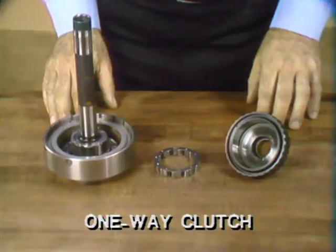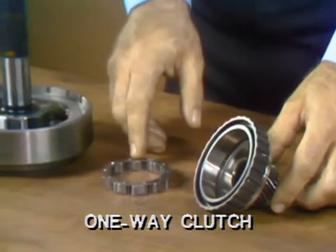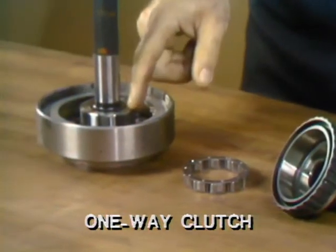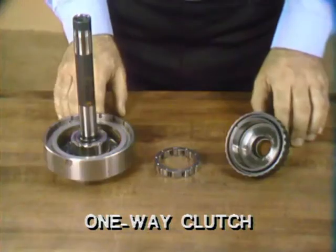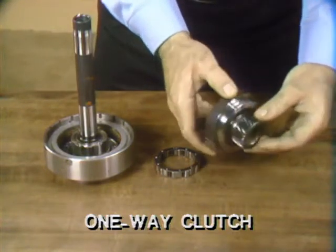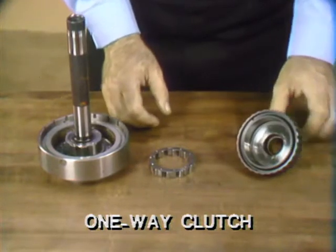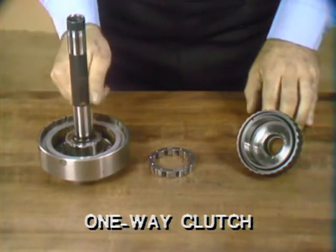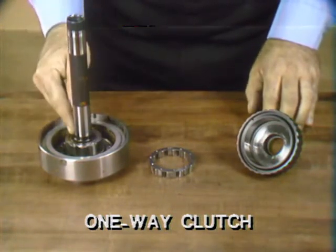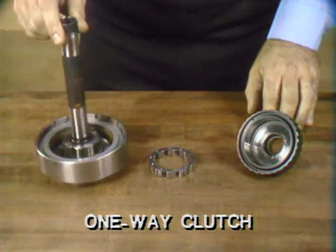The first clutch we will look at for controlling the gear train is the overrunning or one-way clutch. It consists of an outer race, a roller assembly, and an inner race. The outer race of the one-way clutch is part of the low reverse sun gear assembly and will drive the sun gear when the clutch locks up. The clutch inner race is part of the turbine shaft assembly. Thus, the inner race will always be turning at the same speed as the torque converter turbine.